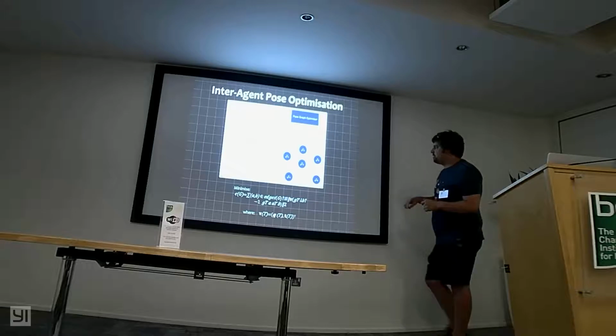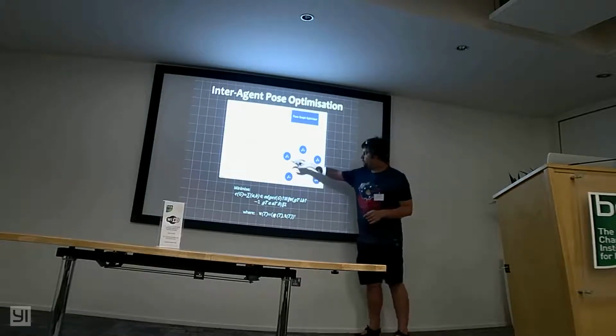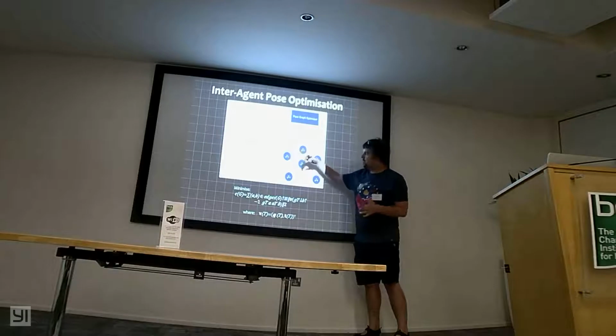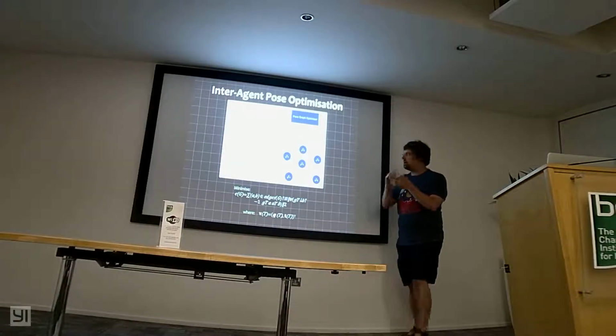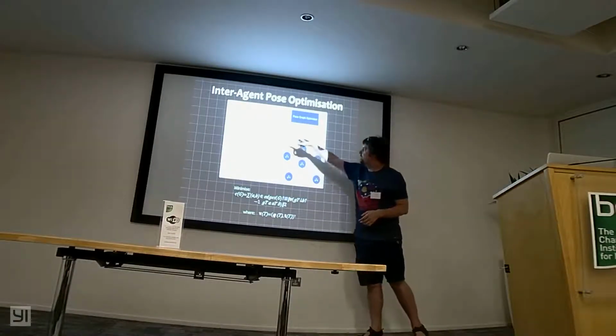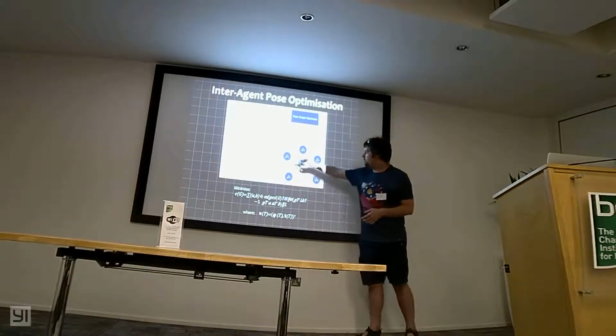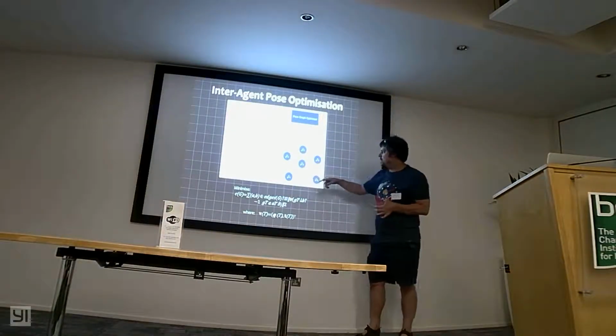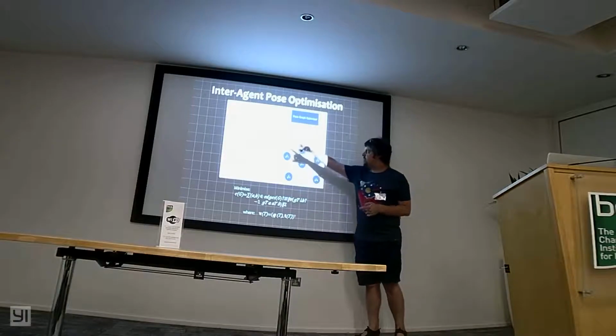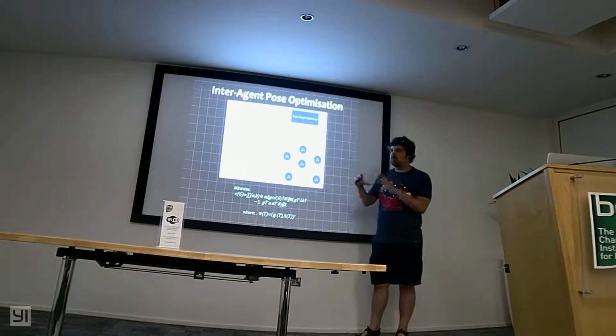And we say that after you've got a certain number of consistent samples between each scene, you get relatively confident about the transform between them. So basically, whenever we add a new sample, we look to see whether we now have a confident relative transform between the two subscenes in question. If we do, we then run a pose graph optimization process based on this.